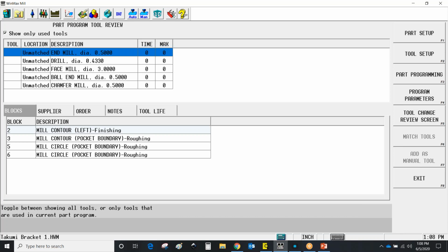And one of the problems we've found with matching is I told you it matches on tool number, description, and diameter. Well, if I'm bringing in a program where all my speeds and feeds are set up to be running steel using a 4-flute carbide end mill, but it would just decide it's going to pick tool number 50, which is a 1/2-inch end mill, but it happens to be a 2-flute high speed, that doesn't work very well. So when you're sharing programs between machines, you'll have your own history or experiences with this, but we typically recommend that you set it this way.